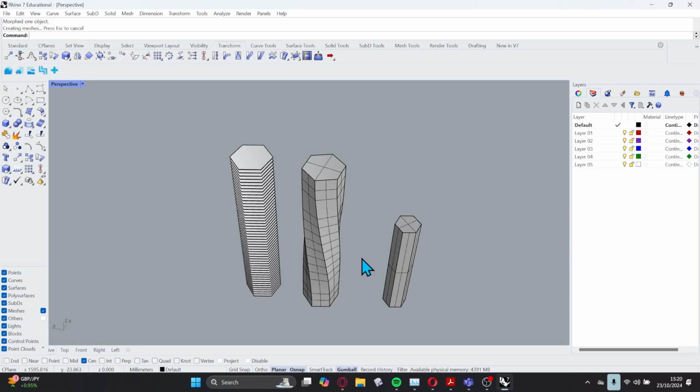Yeah, so let's follow the logic then. Let's say that I'm not here, and you think, how did he do the contours? Let's use some reverse engineering. What are we wanting to create, first of all? Are they floor slabs? They're not floor slabs, are they? We want to create solids. So in order to create solids, we first need to create curves. So in order to create curves, we need to use the curve menu.